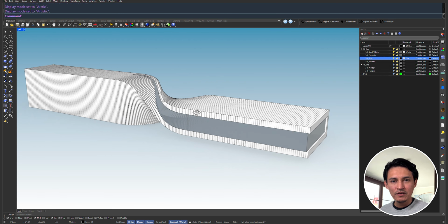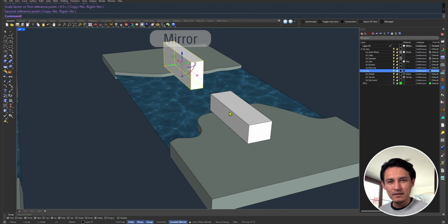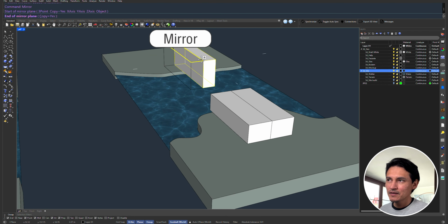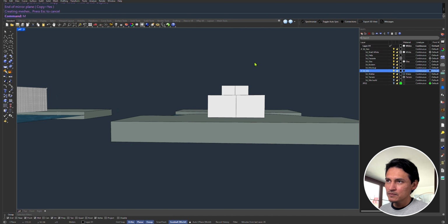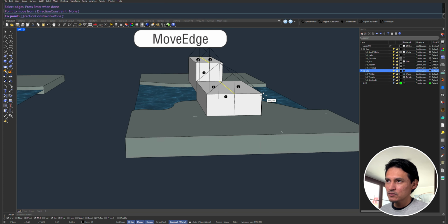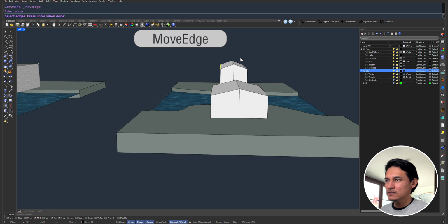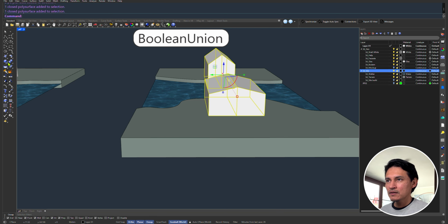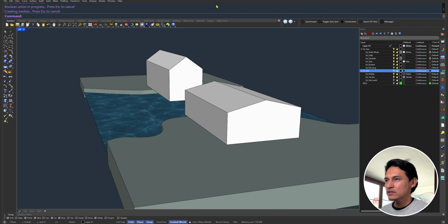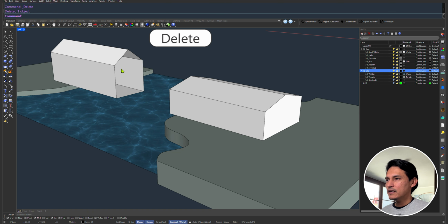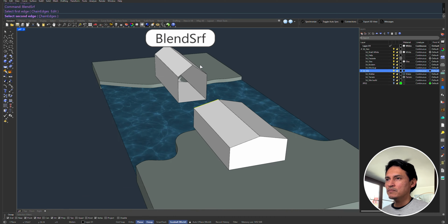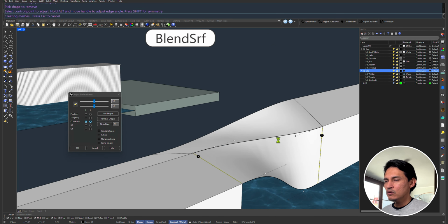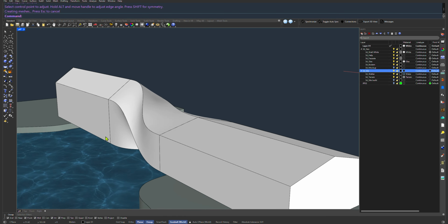But now I'm gonna model it a bit differently. I'm gonna give it a twist, if you wanna call it like that. First, I will create the two volumes, and then I reshape them differently so that the profile has 5 sides instead of having only 4. In that way, the roof will get some inclination, different from the original roof, which is actually flat. Then I continue with blending the edges one by one like I did before, and also rebuilding the surfaces.